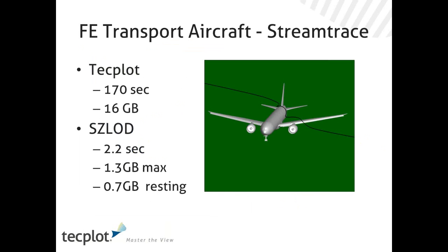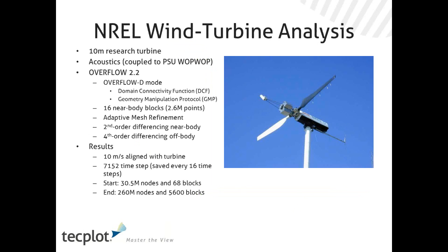Just real quickly, we did do a stream trace. In this case, this is very preliminary results, and it went from 170 seconds down to 2.2 seconds. Remember, this includes loading the data. Standard Tecplot is actually quite fast once you've loaded the data to add stream traces. But if you include loading the data, it's much faster to do it with the Subzone load on demand.